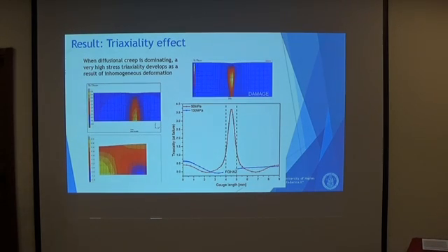But in the second case, the stress triaxiality is very low. It is higher than just at the beginning of the failure, but very low compared to the stress triaxiality in the heat affected zone. Of course, the damage formulation is sensitive to the effect of triaxiality, so we have a localization of damage too.